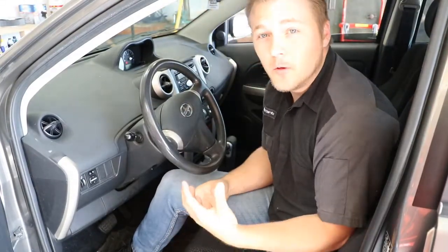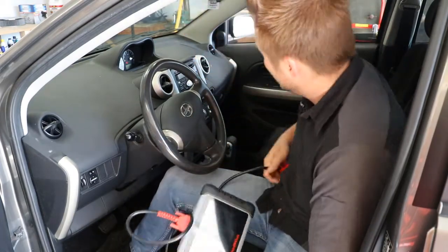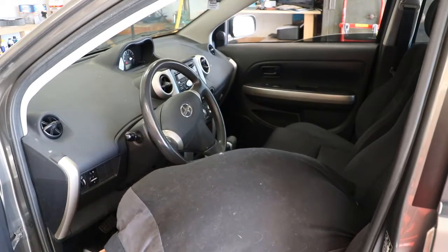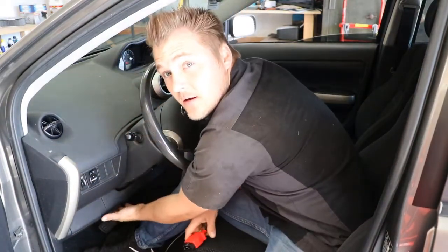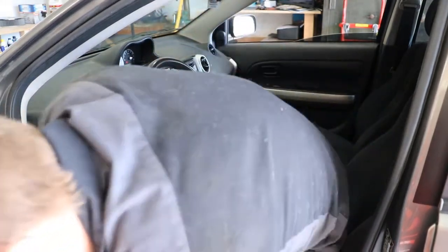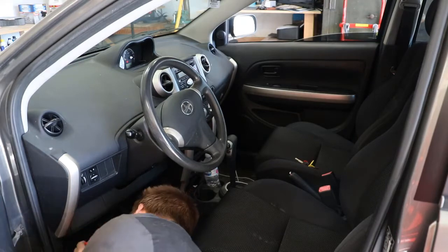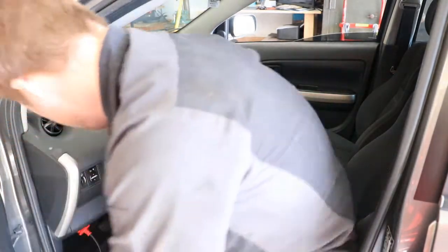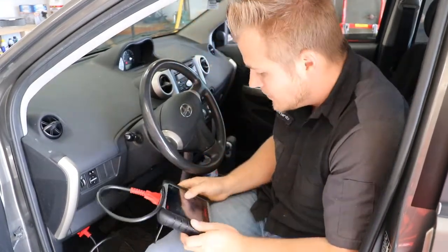Alright guys, so once you get your scan tool and you're ready to get the job done, first of all we need to figure out what the code is. Let me take out the key so it stops beeping here. Underneath the dash, most cars have the OBD2 port. So go ahead and look underneath real quick, find your connector, and ours is going to be a straight-on connection here. So pop that bad boy on, and we're going to hook up the scan tool here.